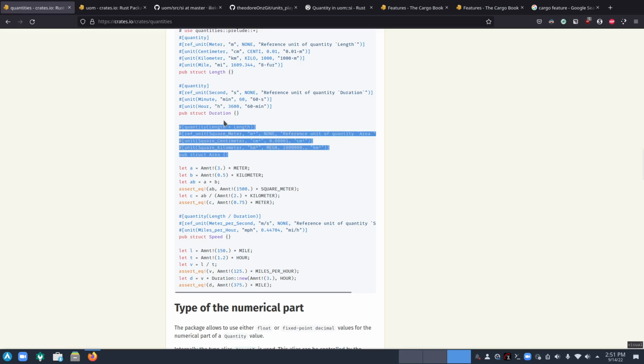If you try to do multiple ways of calculating a quantity, for example energy, you can use energy units, or you can use force times distance. However, you can also use heat capacity times mass flow rate, or m Cp delta T. So it's mass flow rate times Cp times delta T, which is the change in temperature, and then you multiply by time.